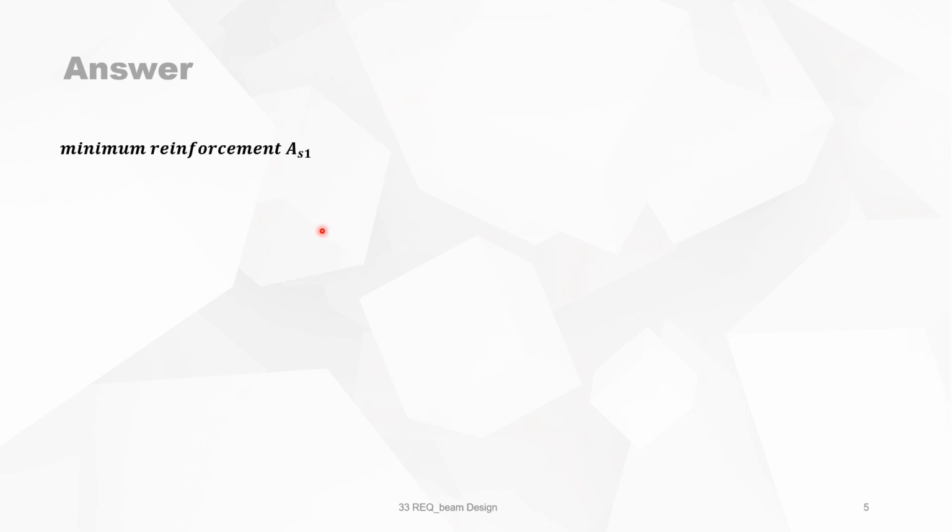Now we look for the minimum tensile reinforcement. We have first to look for crack control. The minimum reinforcement needed for crack control is given by this formula. It is just that the minimum reinforcement must be able to take up the cracking bending moment. In this equation, sigma s is 500 megapascal, it's fyk. Kc is the coefficient for bending, it's 0.4. For tension, it's 1.